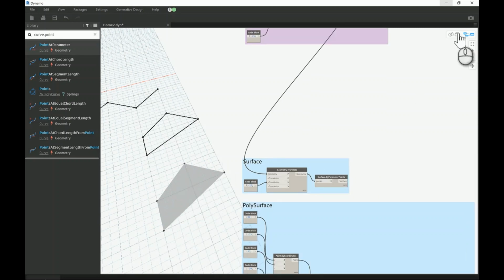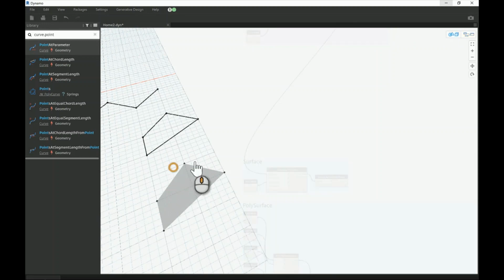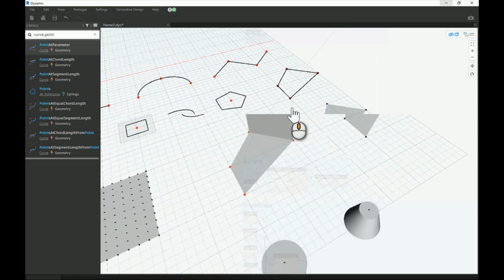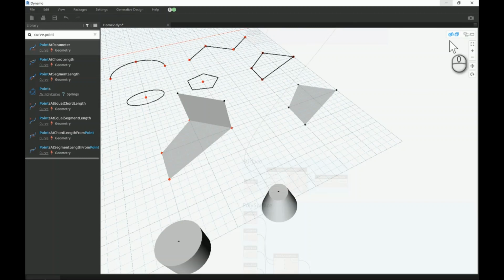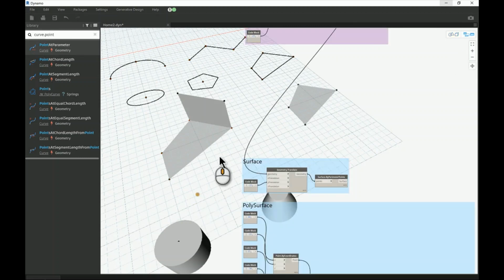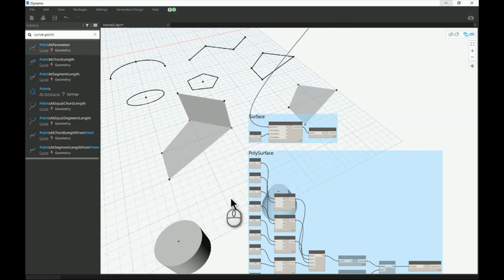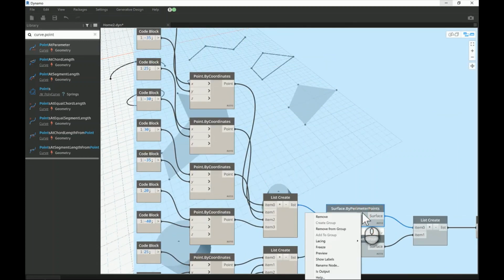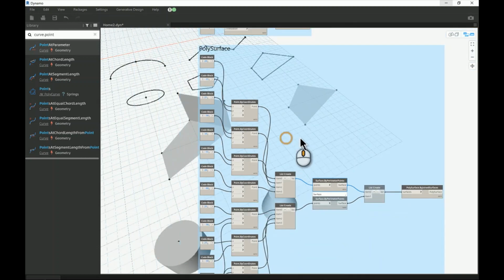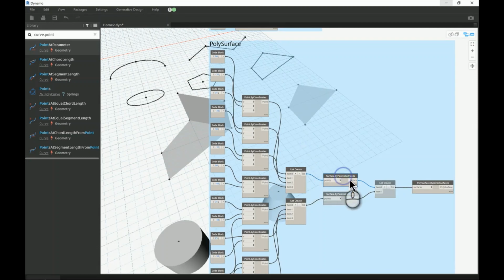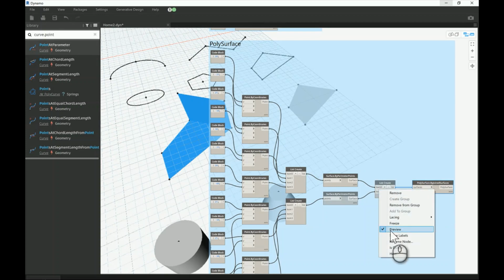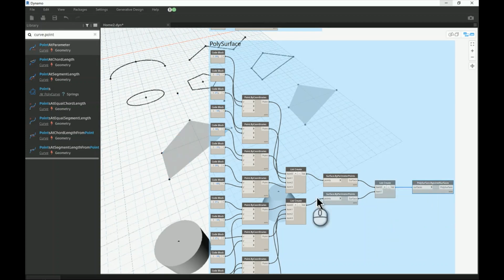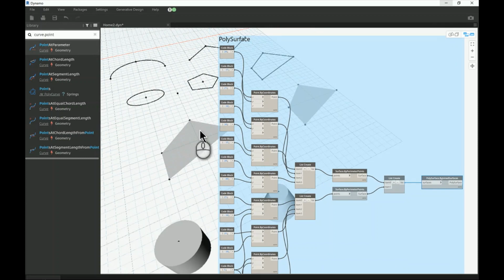So that's the surface. That's a very basic surface that you can create in lots of other ways or types. I just remodeled this one here, a bit differently, I think. So lots of points. I know that's just me being too lazy to do it in a more professional way, to be honest. So we have this one here. You cannot see it actually because this one is on. So let me turn this one off. So the polysurface is just you joining 2 surfaces together.